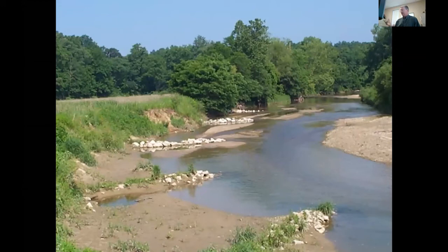So this would be after they've been installed for not too long. The toughest part is getting these crest stones all level and lined up so that one of them doesn't get broken through. They involve a little bit more maintenance than the stream barbs, because if you get water flowing through them to create a void in them, then they have to be repaired with some O&M.